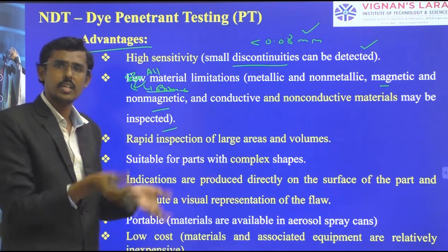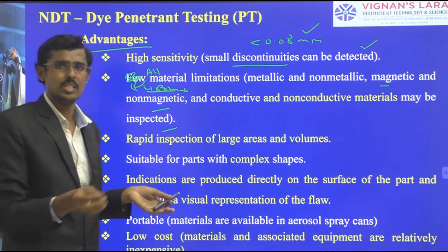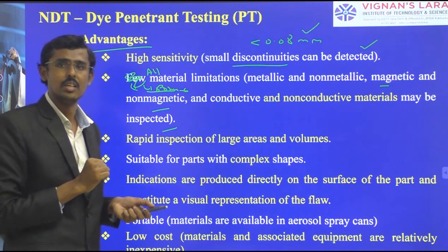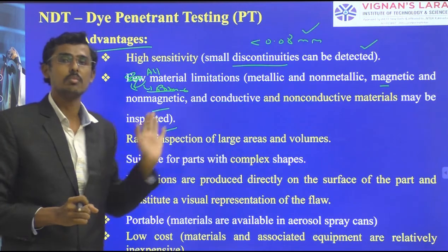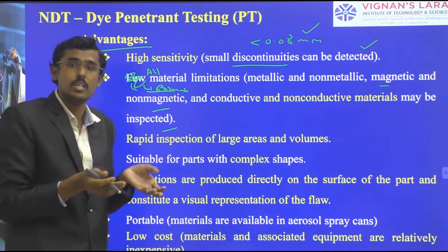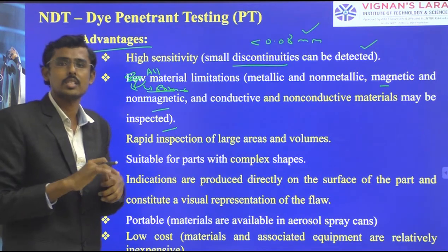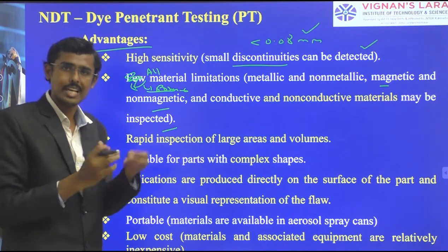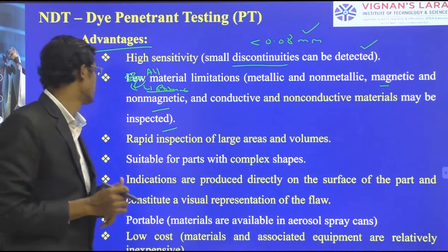We just put the penetrant. There is no reaction that takes place. We just receive color contrast, and that's it. But the chemicals must be removed. The red color penetrant and developer are chemicals that should be removed. But we are not doing any chemical reactions. We are relying on capillary action and contrast colors.